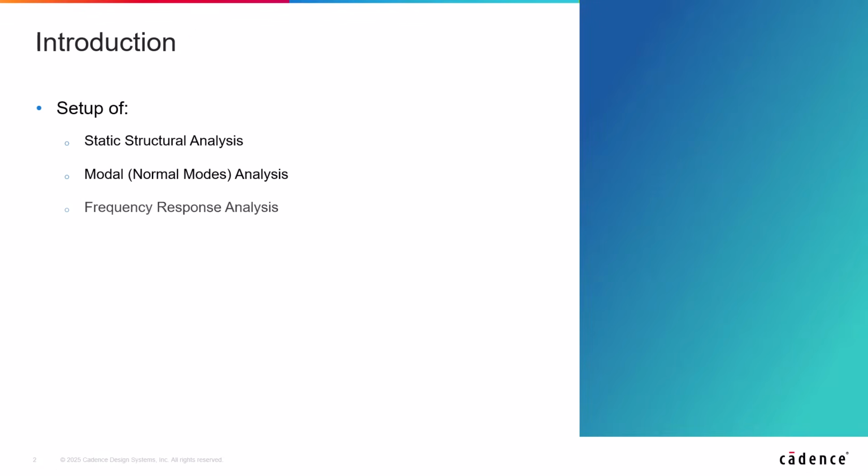First of all, in this demo session, we will set up three types of analysis: a static structural, a normal modes, and a frequency response analysis. The pre-processing stage will be carried out in ANSA, where we will demonstrate in detail how the newly introduced workflow simplifies, streamlines, and significantly accelerates the entire model setup process.